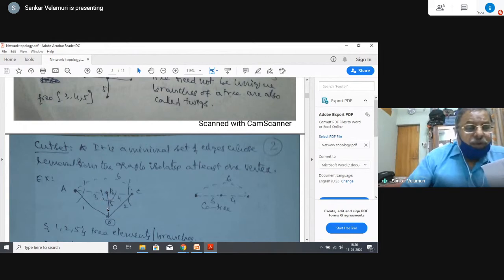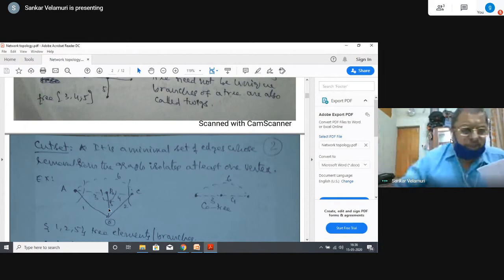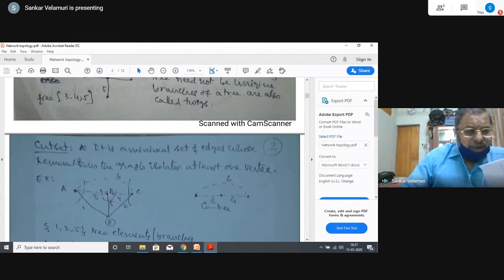Actually, in the circuit, there are 2 voltage sources and 6 elements. For finding the current through each element, one may be tempted to say that I need 8 equations simply because there are 8 elements in the network. But here I require only 3 loop equations and 3 nodal equations, because the node pair voltages are also 3. So some of the questions are related to this. If you follow all these statements carefully, 3 or 4 answers would have been there in this one.